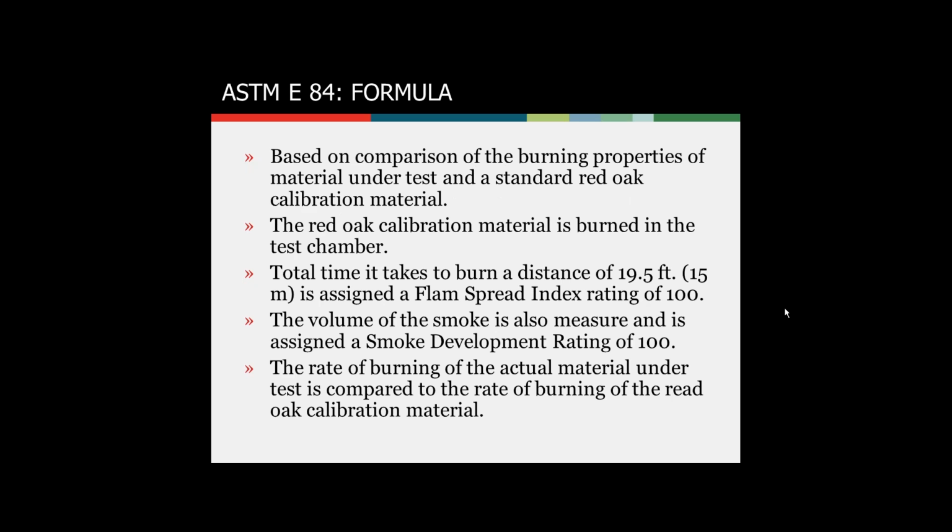This is just a rehash of the way the test standard was developed. Back in the olden days, all tests, even the NFPA 701 that Mark had talked about, were based on a form of testing a cellulosic product. For the NFPA 701, we were talking about fire retardant treated cottons. And for ASTM E84, we're talking about fire retardant treated wood.